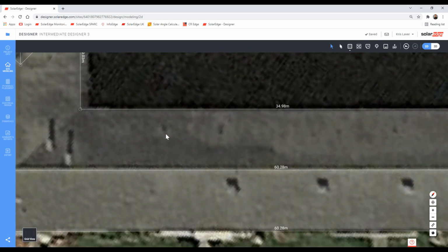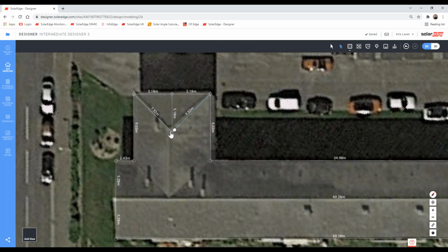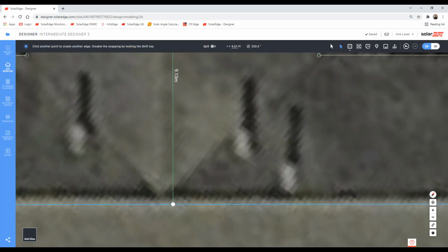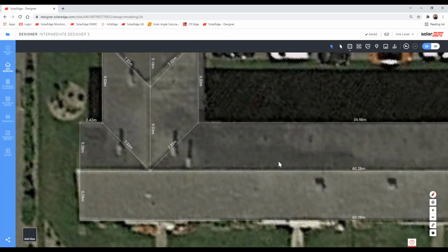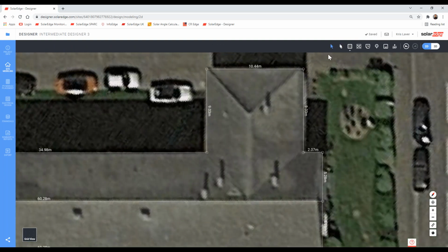So we've got our center line in there. Now let's continue this line as we were, and it could be that it will meet perfectly, or it could finish just before, just like that. So it's not quite meeting the ridge, which is fine. Not all extensions or side parts of the buildings will meet the ridge, and then we're going to repeat that process over here. Draw, find the center line, make sure we're symmetrical here and here, wait for the software to tell me where to finish.